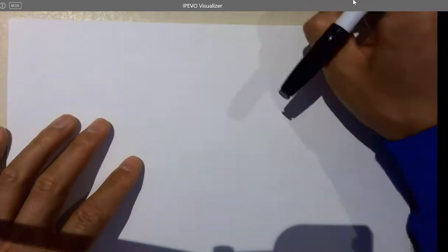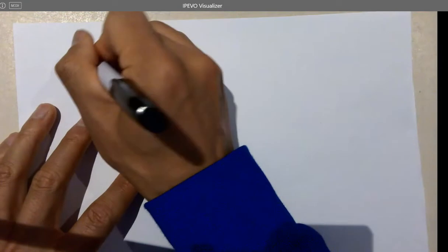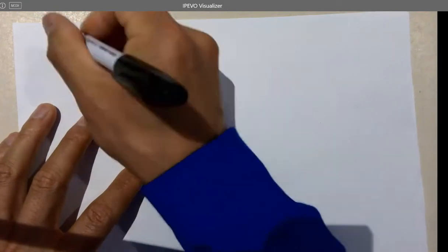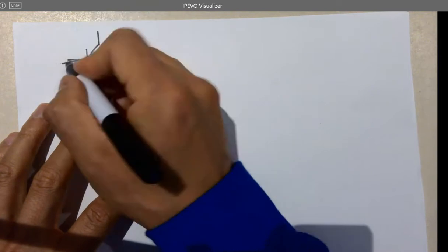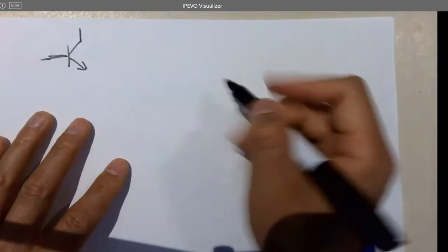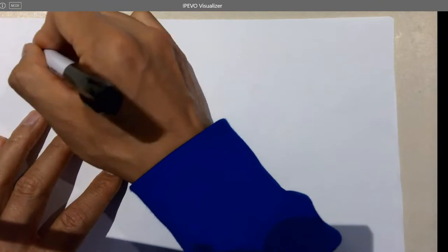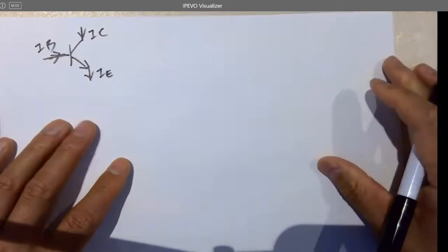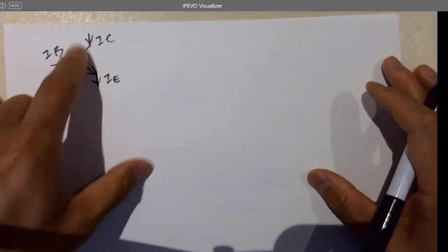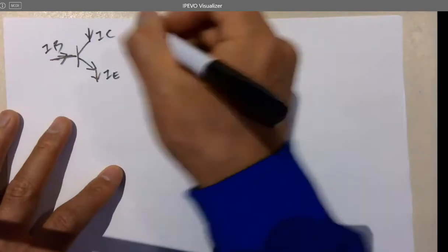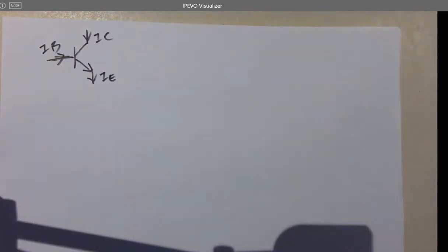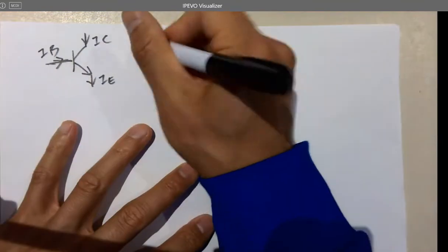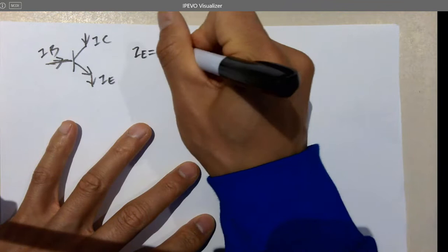Before we do the calculations and give you more examples, let's review these parameters of the BJTs. Here's a BJT transistor, and we're not going to spend a lot of time on the physics and AC properties of this transistor, but just the DC. So here's IB, and that's IC, that's IE. You'll still remember the relationship among these parameters. First, you want to remember these ones, since you are going to directly use them in an exam or quiz. IE is IC plus IB,